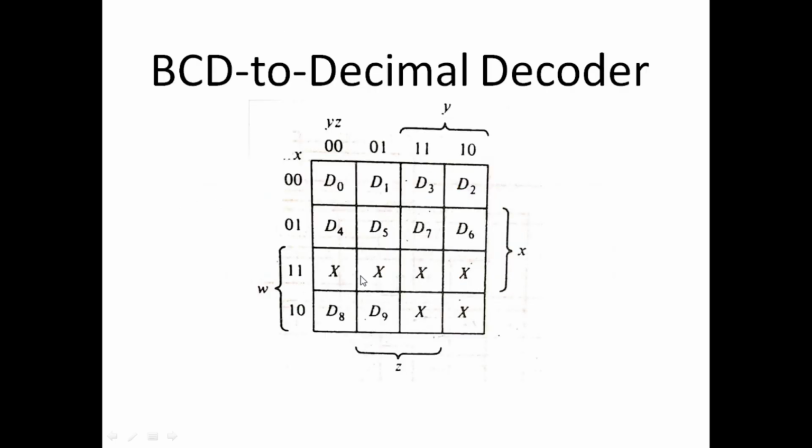So quite similarly, if you would be using a Kmap for every output, then in case of BCD to decimal decoder, the value of D0 would be 1 for the first minterm, which lies here in this square, and for all other squares it would be 0. So the squares in this map with the empty squares are actually squares with 0, and these minterms are don't care.